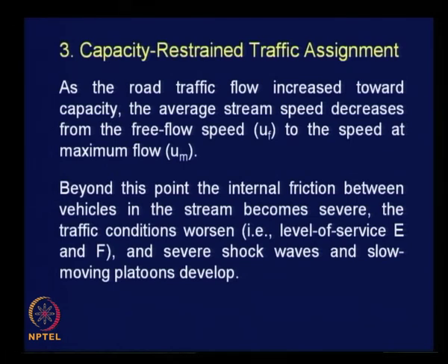Beyond this point, the internal friction between vehicles in the stream becomes severe because of reduced headway. The traffic conditions worsen to give you a level of service of E or F, which is the lowest, and severe shock waves and slow moving platoons develop when the traffic flow increases to reach capacity level.